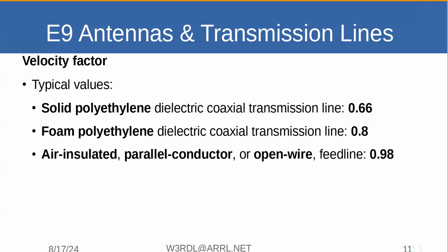And some of the questions where you have to calculate the length of an element will want you to use that correction factor of 0.95. In fact, one of the formulas that's out there for doing it in feet includes the 0.95 factor in the equation. I think it's the one that's 489, and you divide into that.